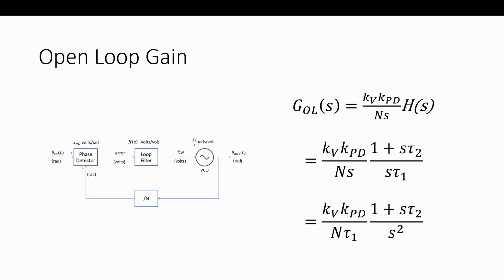We're making a frequency lock loop, and we could get away with the loop filter just being an integrator as a first order loop. Here, we could get away with the loop filter just being proportional and using the integrator that's in the VCO as a first order loop. So it depends on what type of loop we're making and the dynamics of it. And I show some stuff in the backup slides. You can download all this stuff from the schedule, by the way. In the presentation, there's stuff in the backup slides that talks about it.